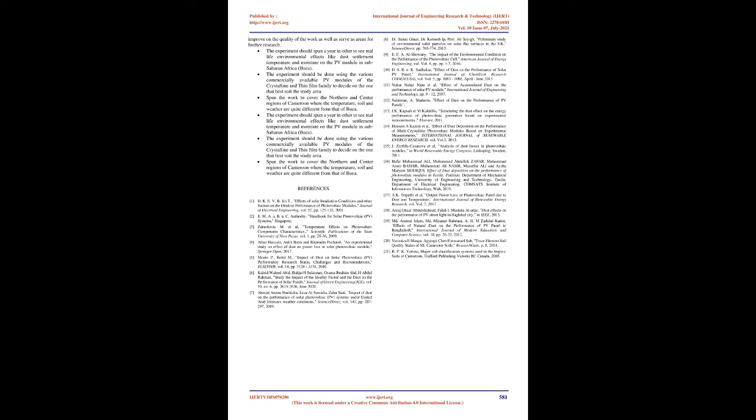The efficiency and output power of the module showed a progressive increase in percentage reduction as dust accumulation increased, taking 5 different mass depositions. This could be a result of the fact that dust particles on the surface of the module scatter the rays of light that were supposed to be absorbed by the PV cells. Also, dust trapped on the surface of the PV module converts the light energy it absorbs into heat energy, which radiates on the surface of the module, thereby increasing its temperature above the standard room temperature desired by the PV module.